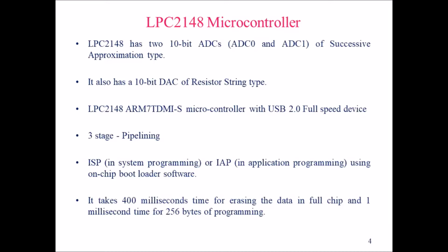It also has a 10-bit DAC of resistor string type. We have one DAC, which is used if you want to convert data from digital to analog. The size of the DAC is 10 bits. So we also have a DAC interface on our LPC2148 microcontroller.